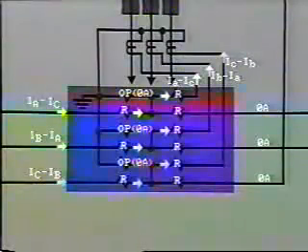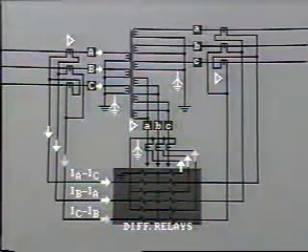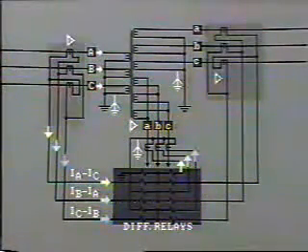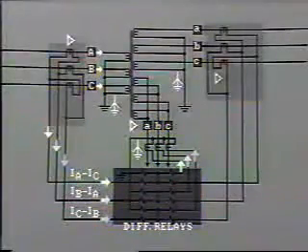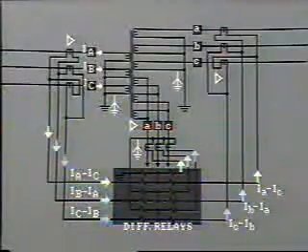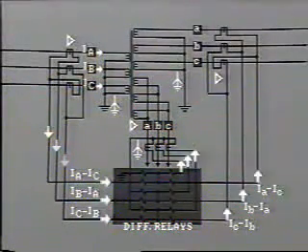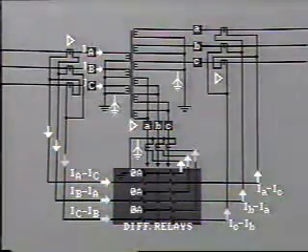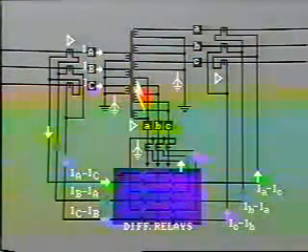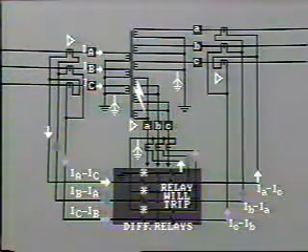The differential relays B and C have similar currents, and the current in their operating coils is also zero. Now, having checked the primary and tertiary windings, let's check the phasing of the CTs in the transformer secondary. These are delta connected like the primary, hence, like the primary, the currents from the relay are IA minus IC, IB minus IA, and IC minus IB. With balanced operating conditions, these three sets of currents cancel, and no current will flow through the operating coil. If an internal fault occurs inside the transformer, then out-of-balance currents flow in the operating coils and the relay will trip.